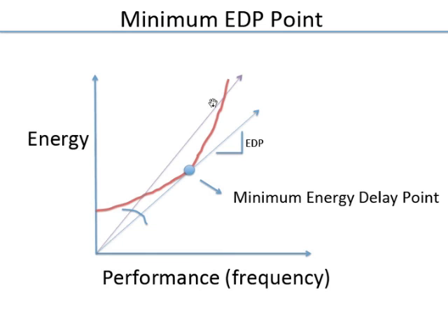It has some shape. It will have this kind of a shape, because you try to push energy, you work very hard. Try to push performance. There is a max performance you can achieve. For example, minimum, equal logical effort gets you to a certain max performance as far as sizing goes. But there is a large energy cost. So as you try to push performance, it's natural to expect energy cost will go up very rapidly. That's why this curve has this kind of a shape. Right? It's kind of like a hockey stick. It just goes up.